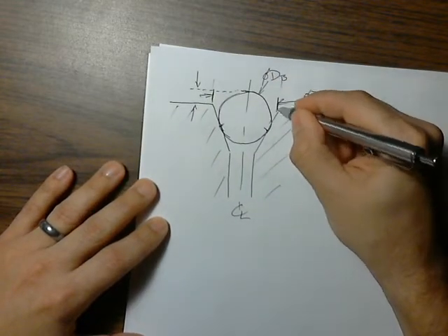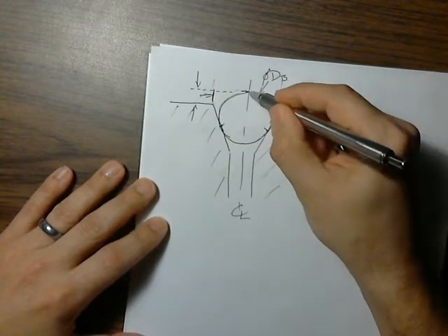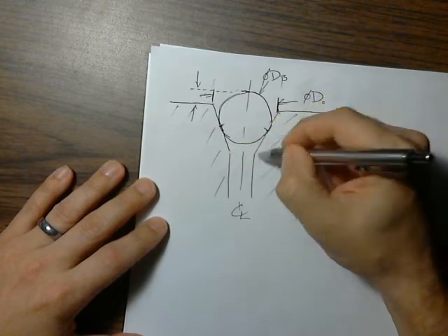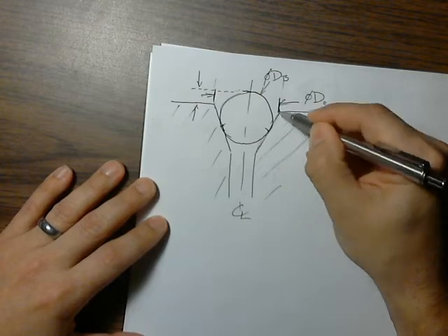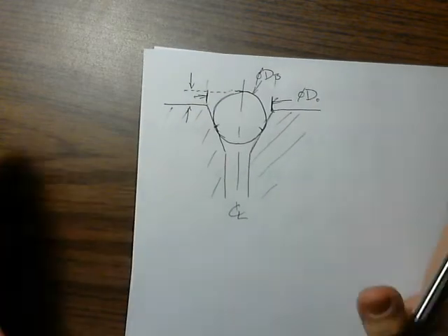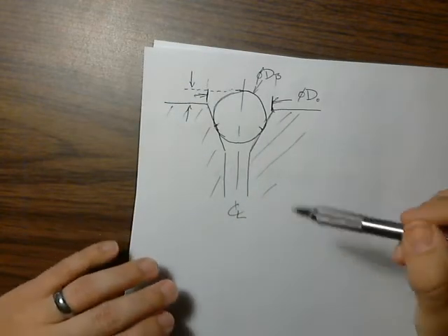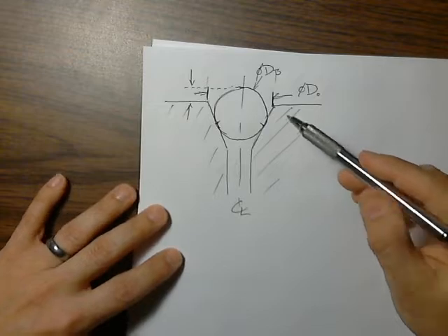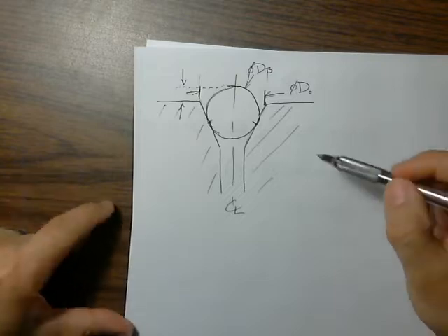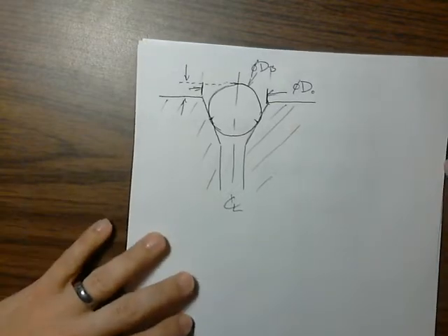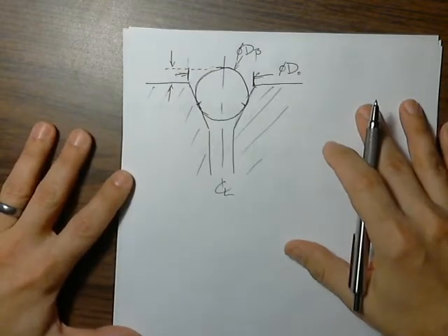So knowing the diameter of the cone where it broke the surface, and knowing how deep down in the hole the ball sat, we could calculate the cone angle of the divergence. This was a method that was easy to implement on the factory floor. You just needed gauge balls and a couple of specially made tools to do this measurement very quickly. And the operators, as it turned out, didn't need a ton of special training. It was actually relatively simple.